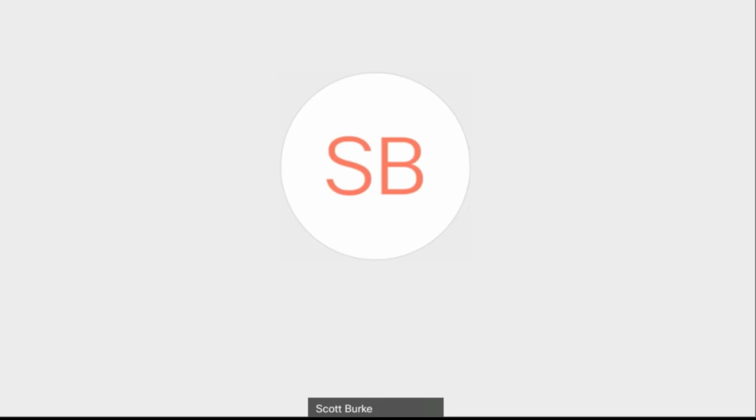All right, so there's another question here. It's at least asking Matt. I'm assuming it's a civil question here. So it says, if using BIM 360 for collaboration, civil team, how does the BIM 360 accommodate changes to external references and data references? Will one team member see changes as data or XREFs are changed by the other team members? So this one's going to behave very similar to what we're seeing now, because with access to BIM 360 docs and design within Civil 3D 2020.2 or later, that is all tying back into the BIM 360 location.